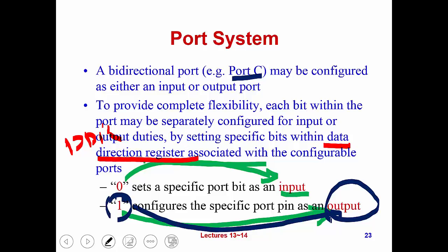So now the value of accumulator A should be 11111111. Then we store this value into DDRC. What's DDRC? DDRC is actually nothing but memory location 0006. That means we set the 8-bit value at memory location 0006 to be all 11111111. And this memory location serves as the data direction register for port C.